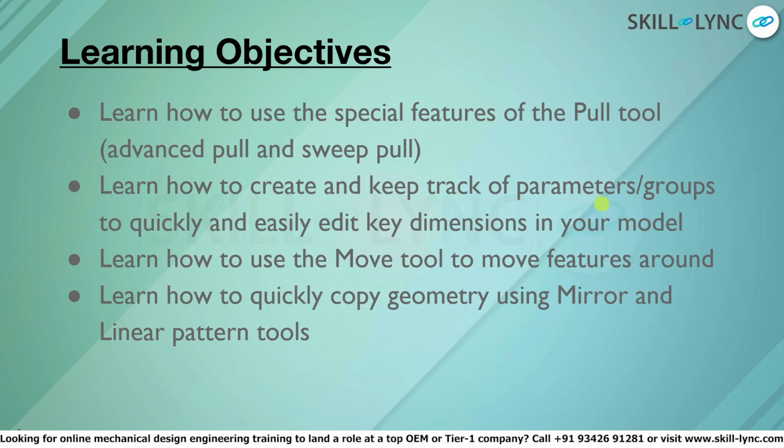The learning objectives for this week are to learn how to use the special features of the pull tool, which is advanced pull and the sweep pull, to learn how to create and keep track of parameters and groups in order to quickly and easily edit key dimensions in your model, getting familiar with the move tool and its features in order to move either different features or different parts of your sketch or 3D model around.